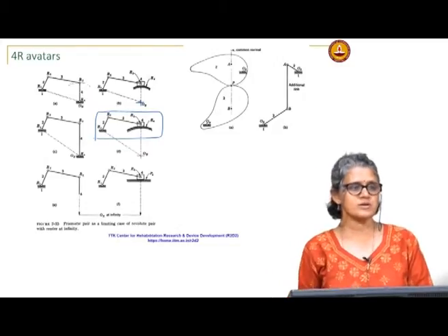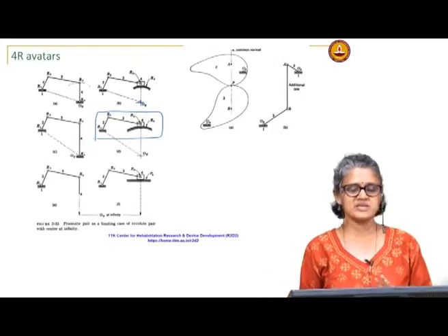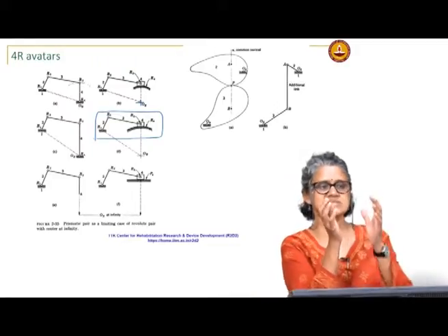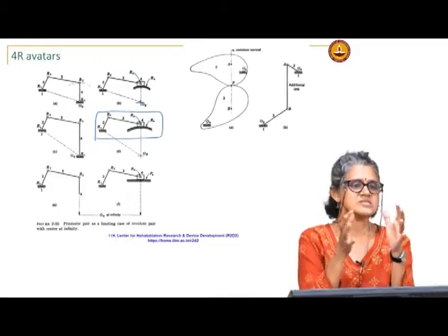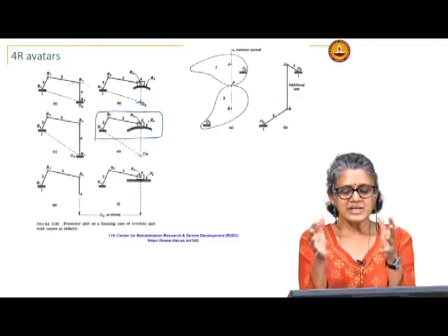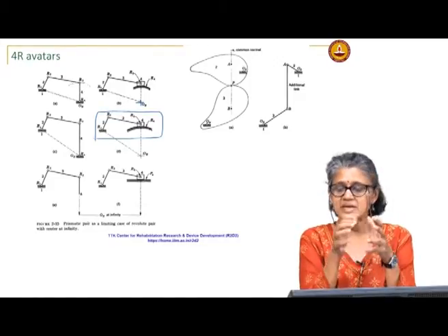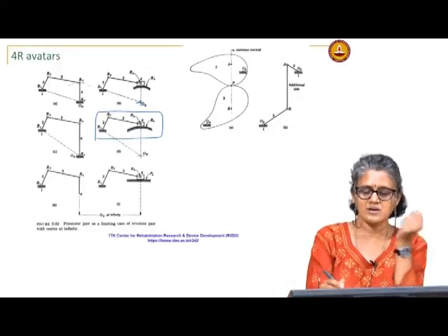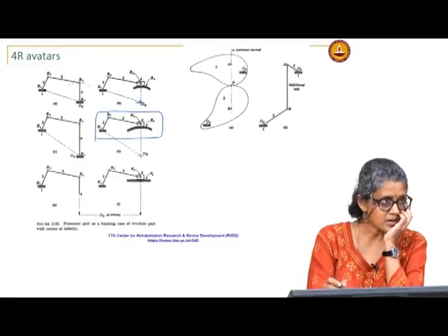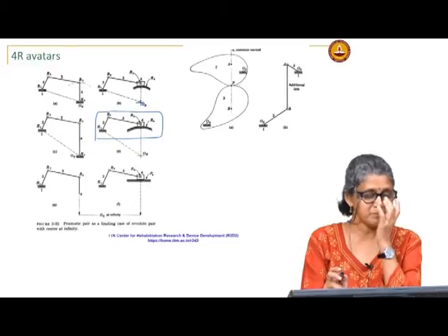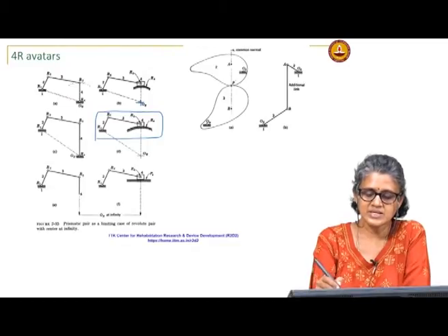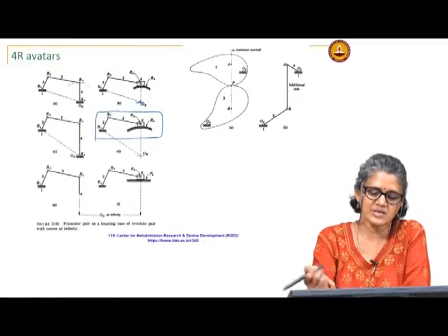This is even more useful when this kind of what we call kinematic equivalence, where the two linkages are equivalent for the purposes of, say, calculating velocities and accelerations. This kinematic equivalence is very useful, especially when you use mechanisms that have higher pairs in them. So, you take for example this cam driving another follower that has this complex shape. Okay. So, in this case, you have cam 2 and cam 3, cam 2 is driving cam 3, say.